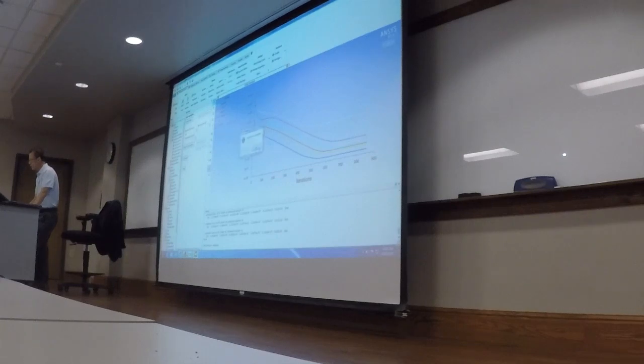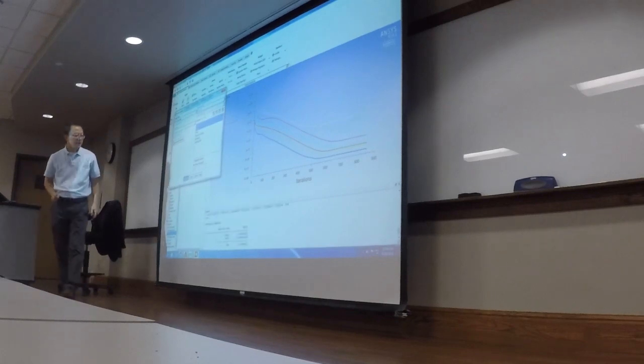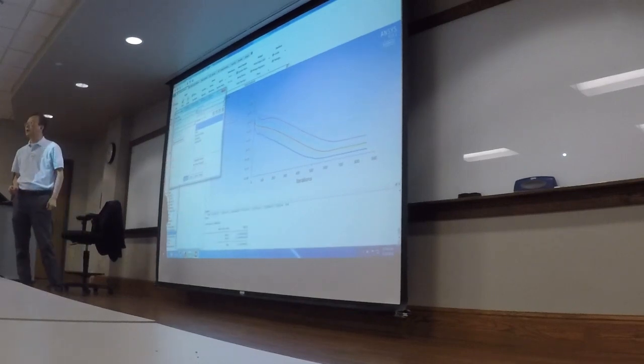All right, I think that's enough. So here, let's go down to see the reports. So go to reports, surface integrals. Let's look at the mass flow rate, exit 1, exit 2. So we expect 95 will go down, 5 will go up. Let's see. 90, 10. All right.